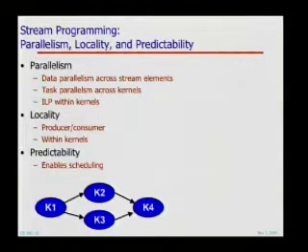So if operating on 1 million things in parallel wasn't enough for you, I can be operating on some of them in kernel 1 and others in kernel 2 and 3 at the same time. So I can have control parallelism as well. And then finally, within each of these kernels, you can analyze the code, and there is some instruction level parallelism in there, often as much as a factor of 5 or 10. So the multiplication of all those gives us all the parallelism we could possibly want to keep our many ALUs busy. Parallelism is usually, not always, but usually not the problem.